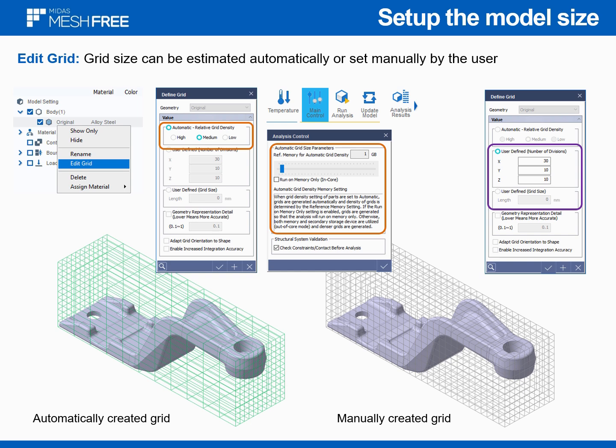So if you want to use automatic approach, then you can click automatic option, and this has been presented in the picture to the left. And another command which is connected to automatic approach, as I said before, is the slider which defines how much RAM will be used. And as I said, this number of gigabytes will define number of equations.